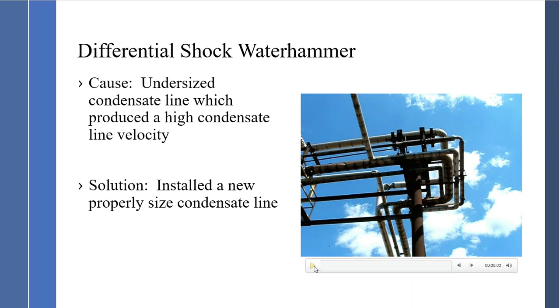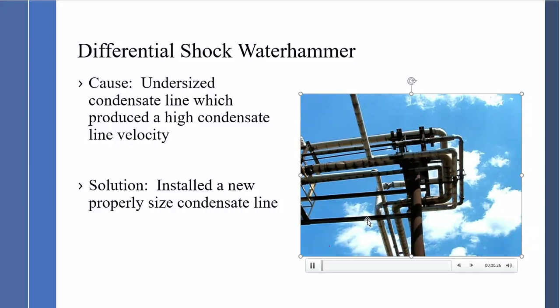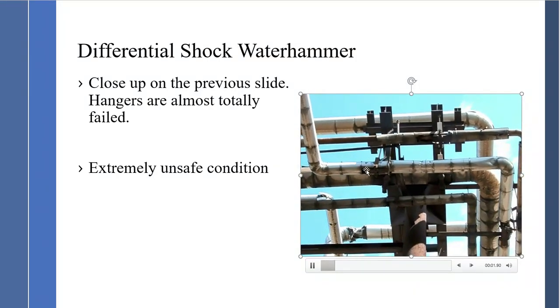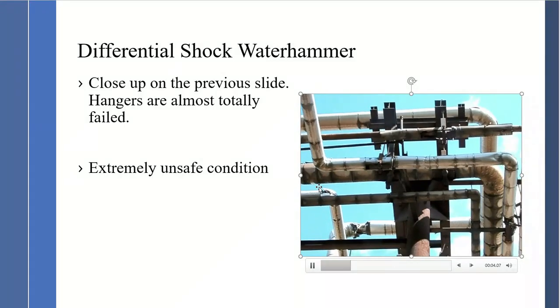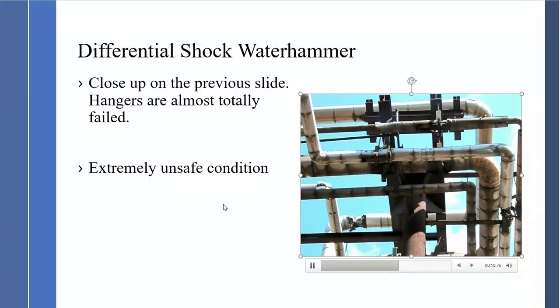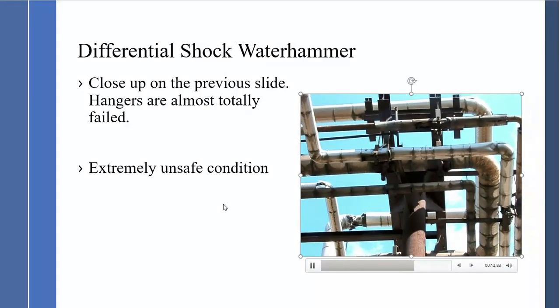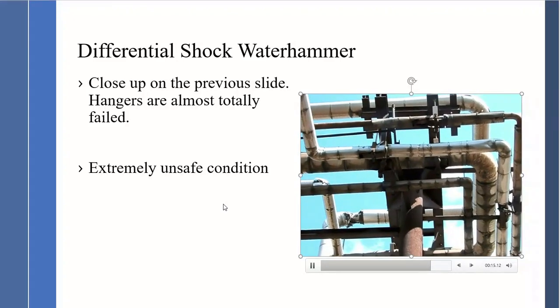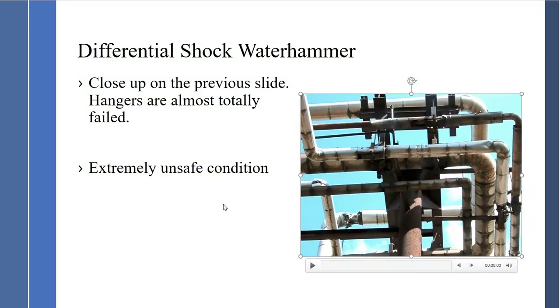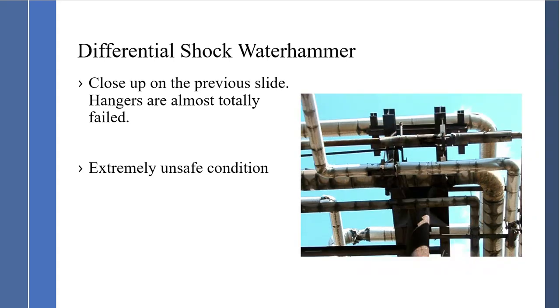So this is just a little bit better close-up of the previous. And you can see the damage to the support, the effects of water hammer. Extremely unsafe condition due to plant personnel being in the vicinity of this condensate line. So the correction happened immediately.